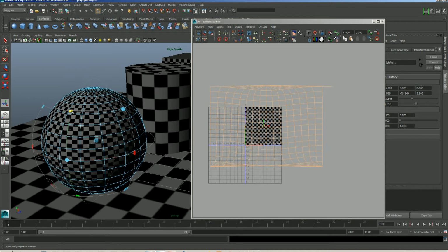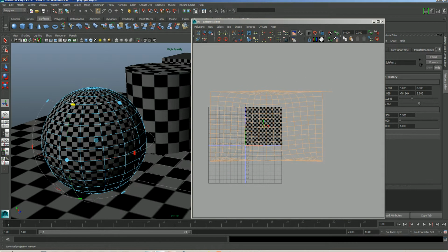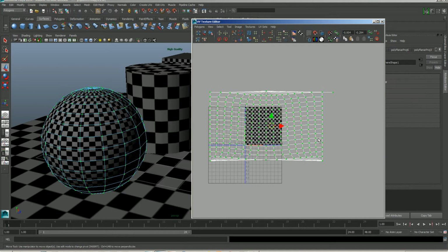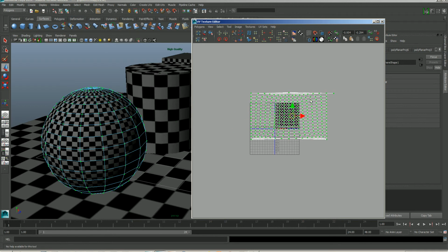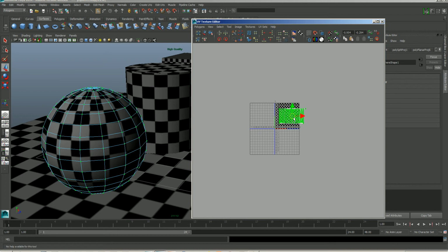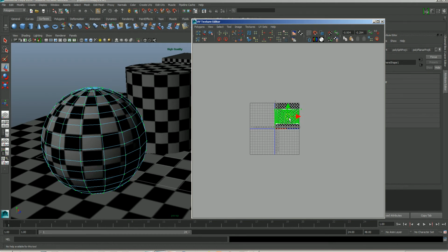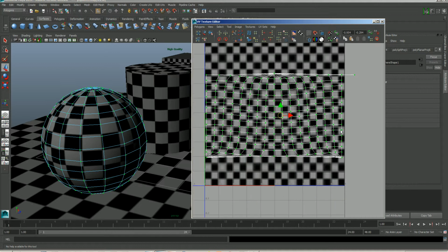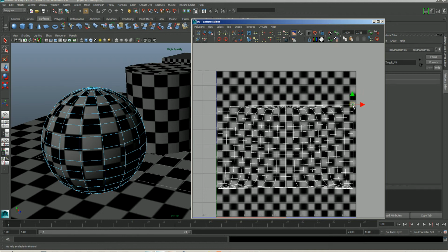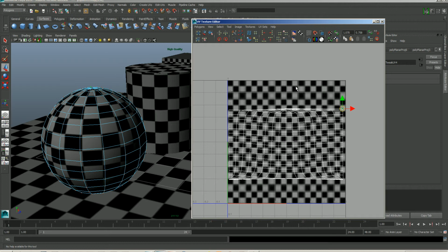Click on the green one here, we can scale this horizontally, vertically. Okay, so about that. Again, control, right click to UVs. And then let's scale the whole thing down. I'm going to position. We have an errant UV here, so let's just grab this guy, UVs, and let's just move this in. And you could spend some time fixing all this up.